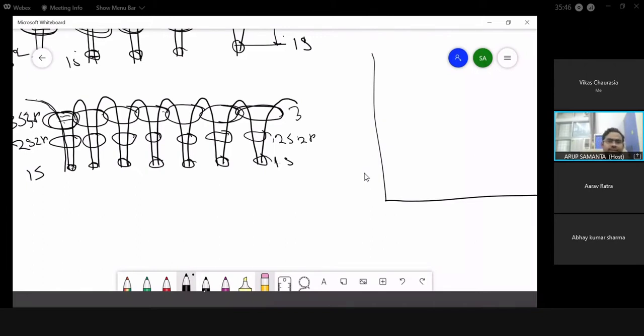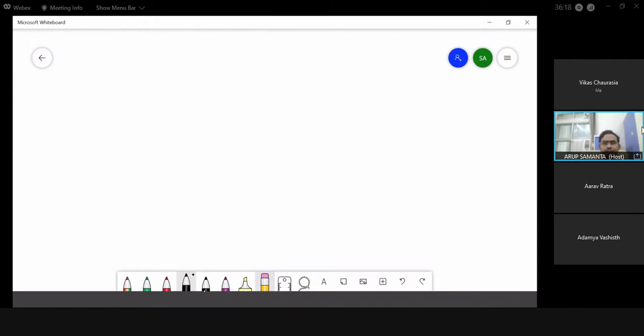But the upper orbit, the valence orbit, will overlap as you make the atoms closer. Orbital overlapping means that energetically they are interacting, which means an electron can move to the other side. From the other viewpoint, due to the Pauli exclusion principle or the electron interaction, the state will split. Initially, I consider the distance between the silicon atoms to be high.